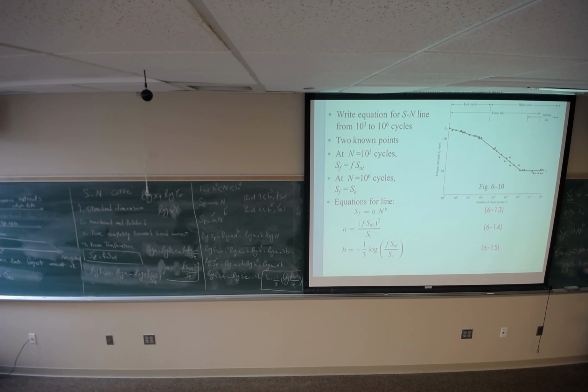What you need to do is just set sigma reverse equal to SF, A times n power B. Sigma reverse divided by A equals n power B. How can I find n? Just apply the log. Log of sigma reverse divided by A would be log of n power B. B is coming out of the log.